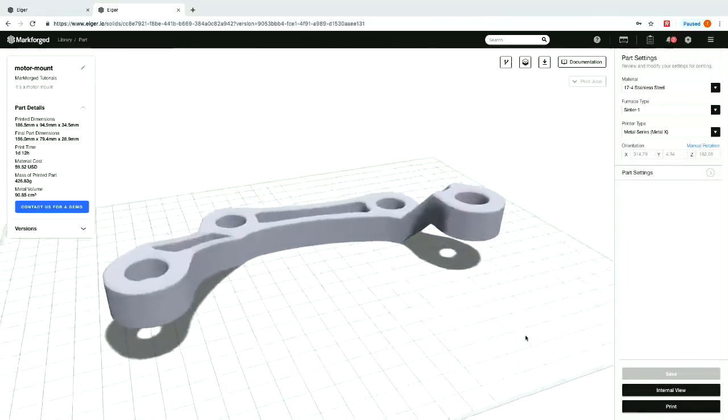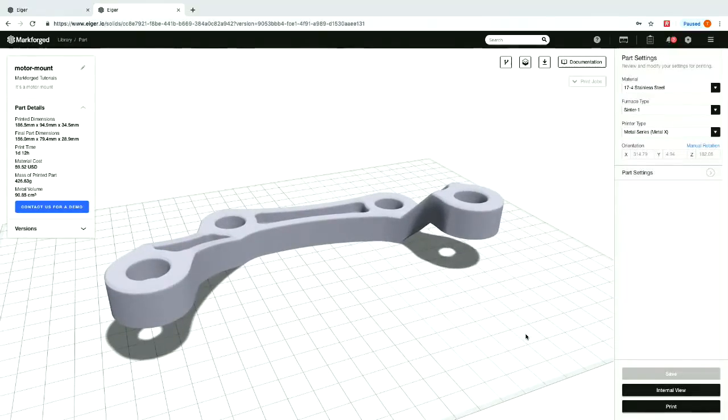And so while you cannot integrate it into assemblies midway through the process or print it onto assemblies, what you can do is easily create assemblies out of the part. And what you get out of the sintering furnace is just like another H13 part. You can harden it, you can finish it, you can polish it, you can post machine it if you would like. And so in that way, it's like a part made through any other process.